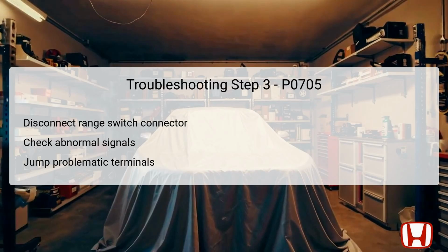Once this is done, turn the vehicle back on and again utilize the HDS to review the signal inputs for the switch. If multiple inputs still indicate on, the transmission range switch may be functioning correctly, suggesting that attention should shift to wiring issues. However, if the expected signals are not achieved, it's definitive that the switch is faulty, requiring replacement.